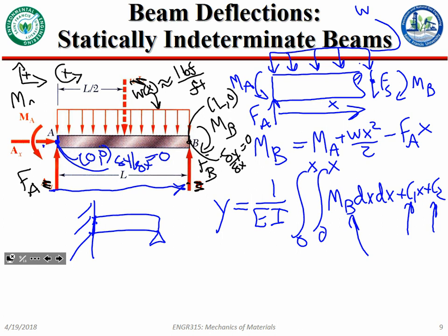All right, questions? Why isn't there another force in the x direction that was A? Say again? Oh, it's because this is actually 0. They put it there to say you could have one there, but you're not really. I mean, for large deflections you will, but we're not caring about that right now because that violates our assumptions. If I summed all the force in the x, there's nothing else acting in the x direction, so it would be 0.